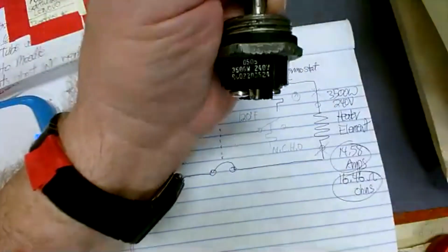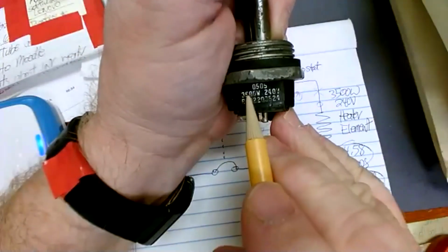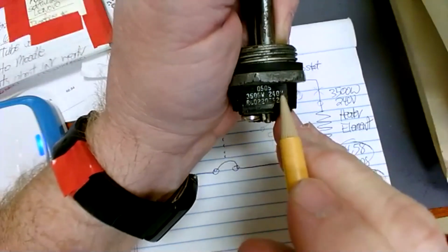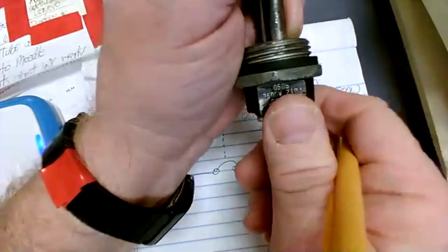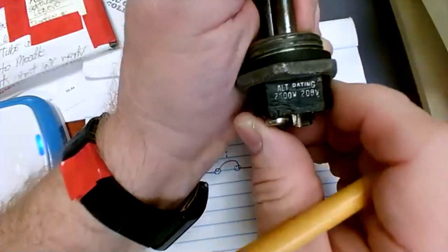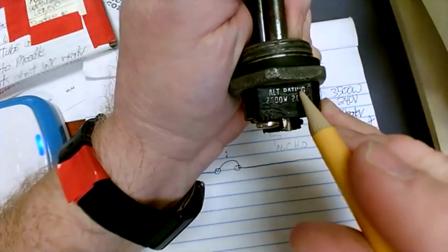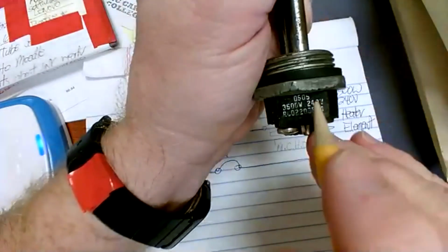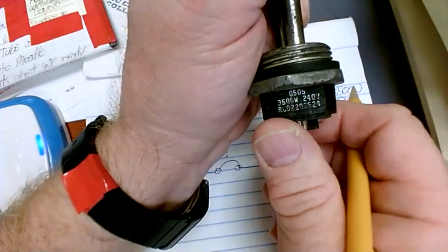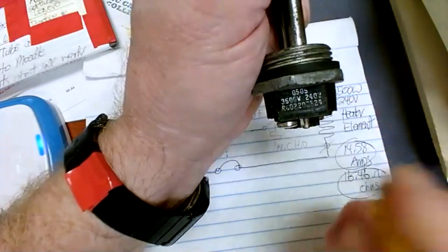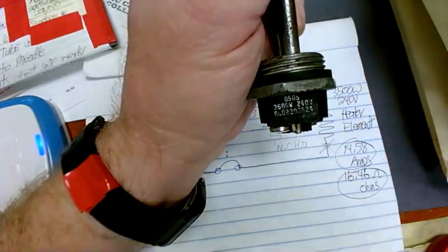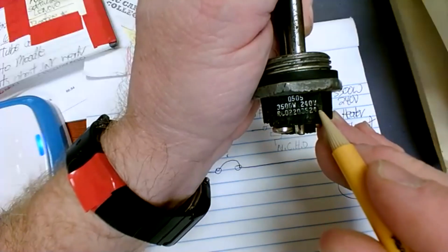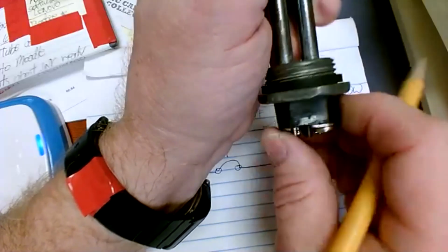I'll add one more thing about this heater element. This thing is rated, it will consume 3,500 watts of power if you put 240 volts on it. Now look at here, I'm going to rotate it around, and what do you see now? Alternate rating. The alternate rating would be this at your house. If your house doesn't have 240 going into it from the outside, like some houses don't, the maximum would be this. Actually at my house, it's about 249 volts coming in from the power company. It's almost 250 at my house.